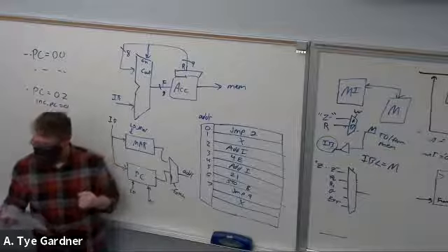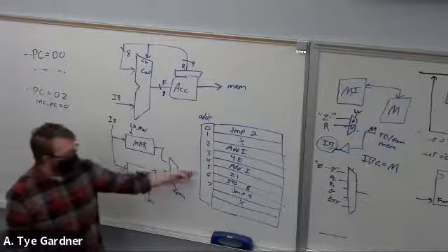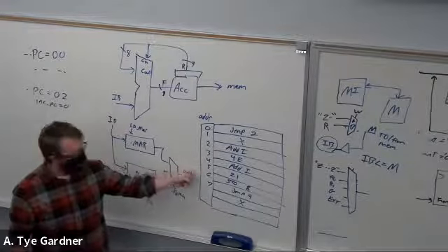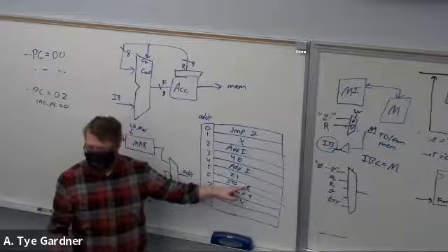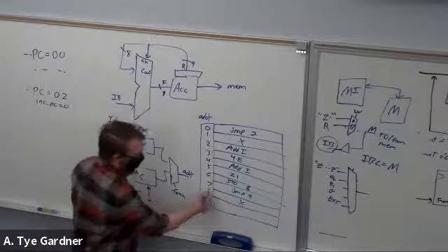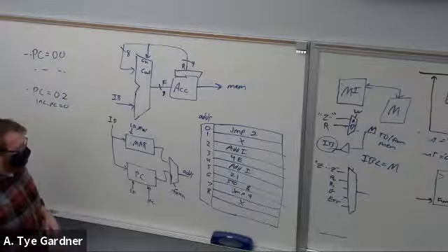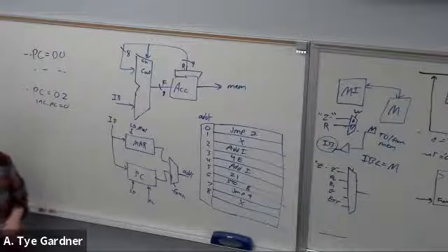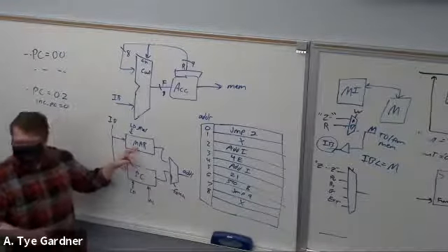So when you say store 8 and 6, is the MAR remembering 6 or 8? The MAR is remembering 8 because the process counter is 6. Okay. The location that I want to store to is 8. And then if you ever wanted to fetch that number again, you just have fetch equals 0, and your address would go back to 8 to grab that value. Exactly. Okay. So it's fetch 0, that MAR, until we update it.